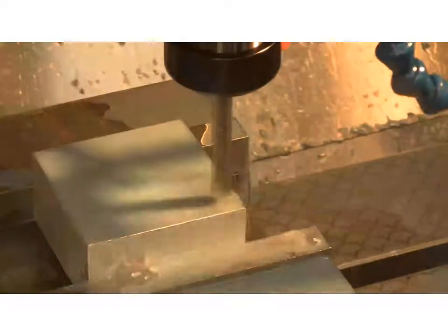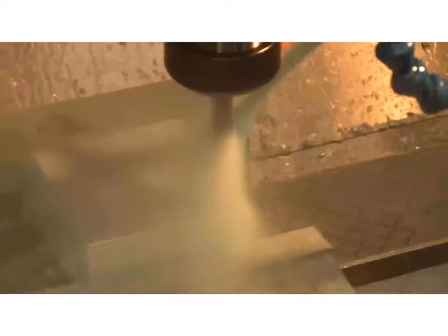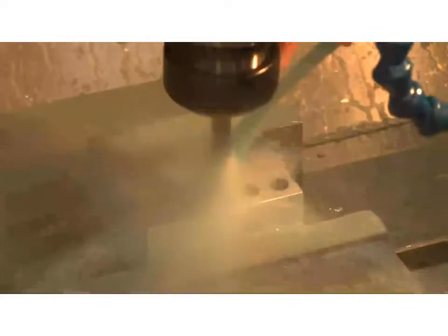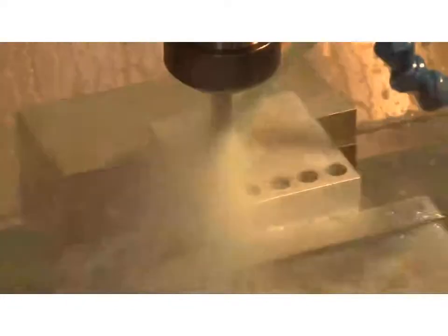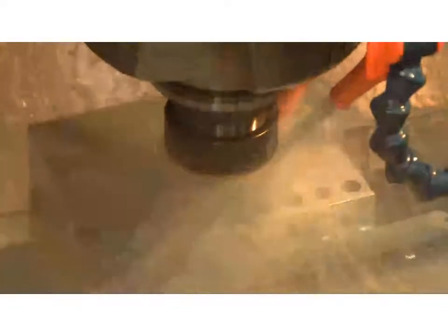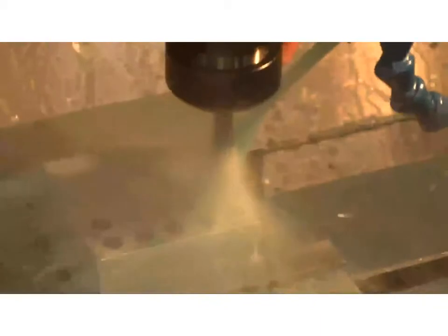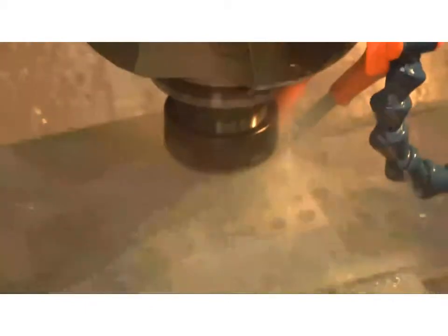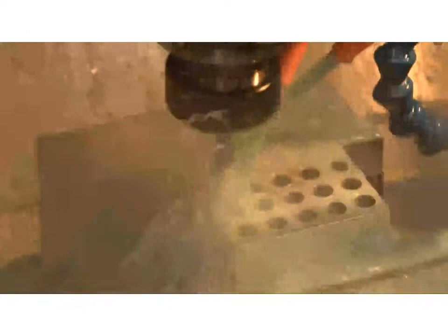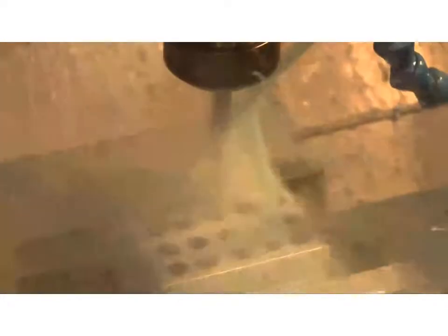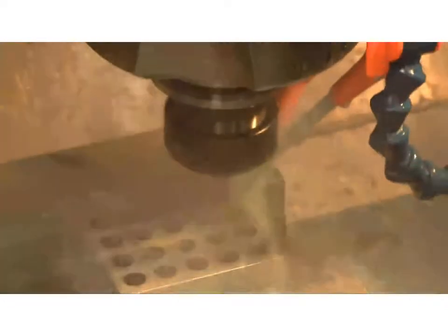Okay, I'd like to give a special thanks to Morrison Tool Company for allowing me to do this video. This is their 3-tooth aluminum drill, and of course it's drilling in aluminum. What I thought was interesting here is that we don't have the spindle coolant. We're just using a regular coolant line, and you can see we're blasting through that quite fast. The 3-tooth drill, like I said, is a really nice drill for staying on location, staying on size, and processing quickly. Even if you don't have the latest machining centers with the coolant, it doesn't mean you can't take advantage of some of this technology.